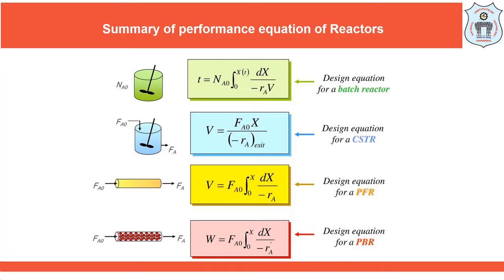Okay, for example, if you consider a plug flow reactor, we know the performance equation is tau by Ca naught equal to integral dXa by minus Ra, where the integration limit is from Xa1 to Xa2. Similarly for CSTR we know that tau by Ca naught equal to (Xa2 minus Xa1) by minus Ra. So for plug flow reactors the volume of the reactor required is the area under the curve, whereas for the CSTR reactors the volume of the reactor required is the rectangle.